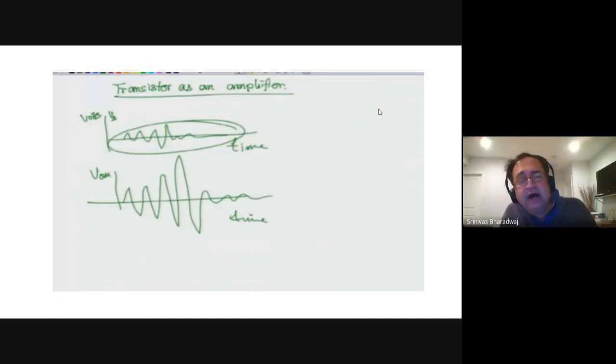Okay, so the second side of the transistor, that is the CE side, operates partly in reverse bias, right? So because the CE side operates in reverse bias, if you have a VS signal which is small, the corresponding voltage across the load will be very big. So that is what amplification is all about. This incremental signal on VBE produces a faithful amplification.